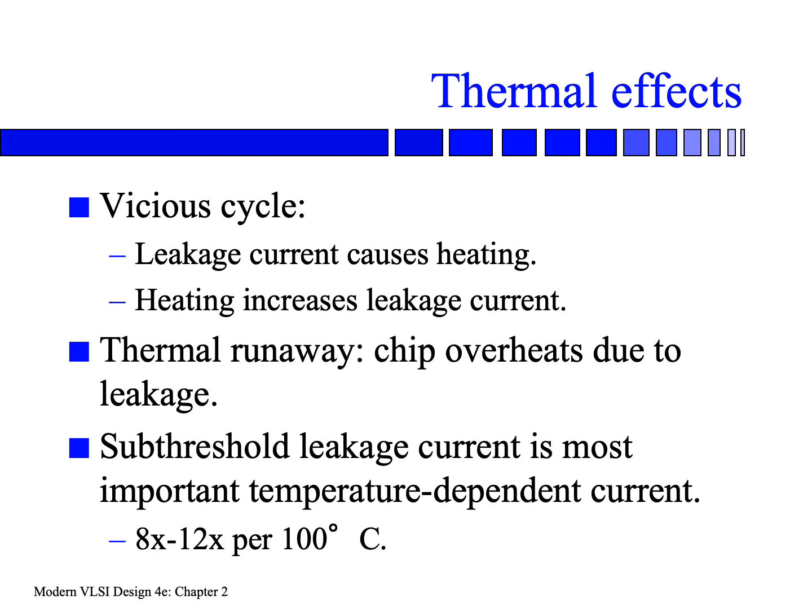In general, the CMOS PN junction can only sustain no more than 150-degree temperatures. Otherwise, the PN junction just breaks down. So if you look at all the Intel chips, pretty much they control the temperature around 100 degrees. More than that, the chip will either be temporarily shut down, or they do some throttling, reduce frequency, all kinds of tricks to reduce the power of the chip. That's pretty much what all the major chip companies are doing right now.